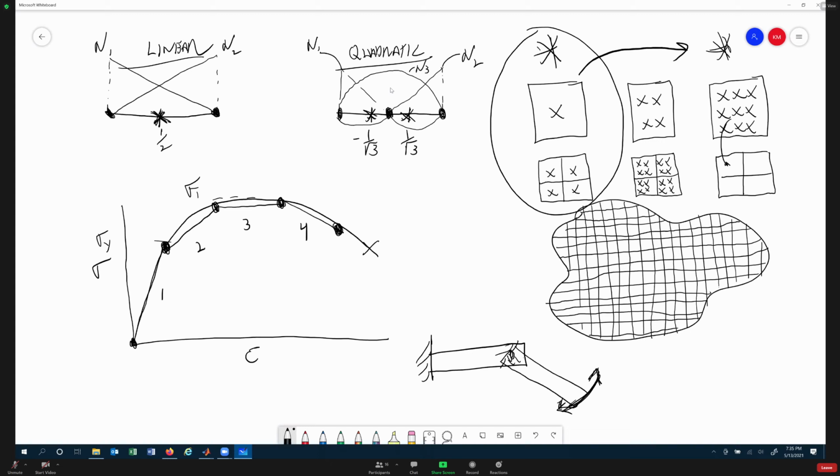And it may be like in this particular thing, maybe all you care about are the stresses right around this hinge, and you don't care about anything out here or out here. So maybe these super coarse elements out here are perfectly fine because they just have to exist. They have to be there. And you want a super, super dense fine mesh in here. And maybe you want some of them quadratic, whatever it may be. You want to make this an intelligent decision.